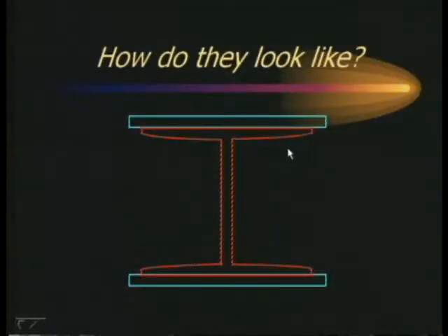And will you see some different built-up beams? Here they are. Here we have an I section, okay, and the plates are added to it. One plate on this side, one plate on this side. So you have a rolled steel section, I section, and plates on either side. Such a beam is called a built-up beam, a plated beam, or you can also call it a compound beam. And how about this?